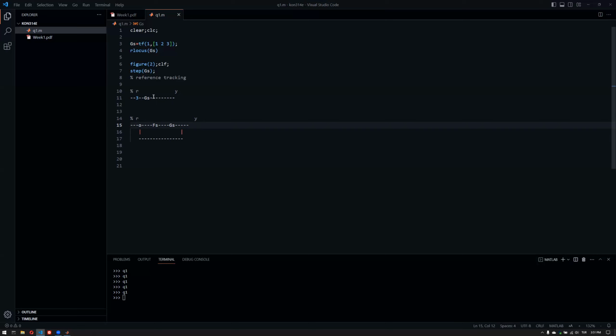That was not possible unless you were looking at helicopters or flight systems. Those are unstable by nature, or some pendulum or stuff like that. There are unstable systems in the real world. But most of the systems that we are considering in this course are stable by nature. Now here you have to be careful choosing the controller because you might end up in instability, and that is only your fault. If the closed loop system is unstable, then that's your fault. That's it. The system on its own is probably stable. Therefore, you have to take care about that.